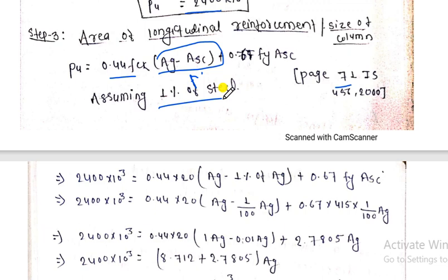याद रहे, for earthquake resisting design, we will always design by considering percentage of steel greater than 2%, 2.4%, 2.5%. Sometimes it may be considered as 3% also. So as it is not earthquake resistance, we consider it as 1%.